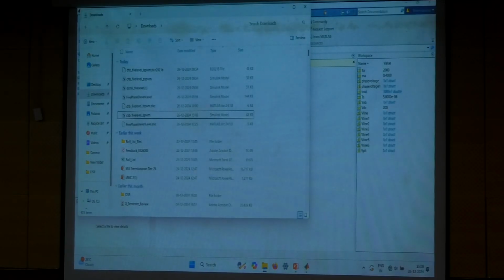We need to monitor the capacitors. Now you have DC sources, so you're not worrying. But if the capacitors are not balanced, all the voltage levels are not the same. You will not get clean waveforms. The voltage waveforms will change. One height will be 90 volts, another 92 volts, 93 volts, 89 volts. You will not get cleaner waveforms. That is fine.